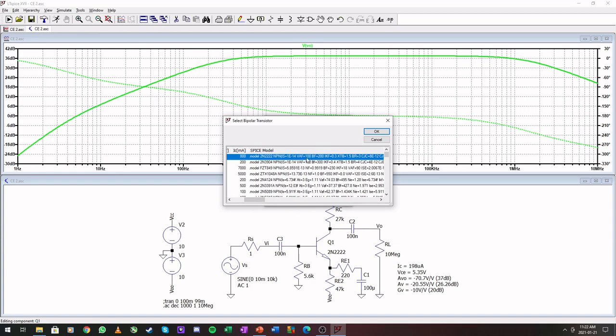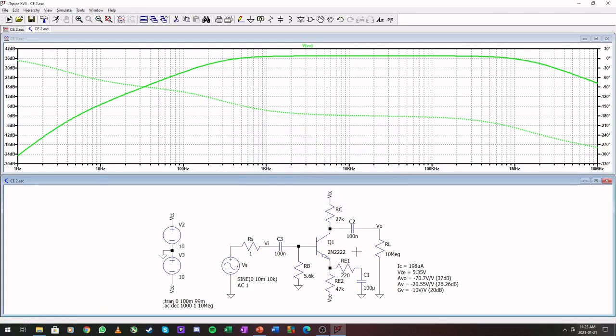That is the early voltage. Okay, so it should be 100, not 50. 50 is still fairly large for the problems that we're doing here, but it won't have a large effect. And the forward beta is 200. So you can get all this information from the SPICE model that's programmed here. In any case, this design checks out.